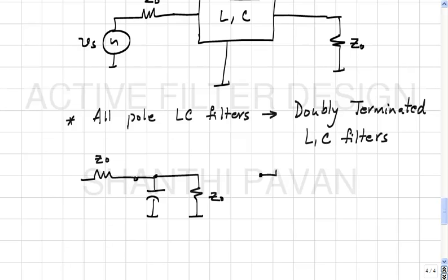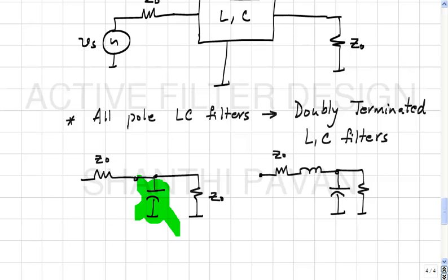When I want a low pass filter, if I want to use an inductor, then this is a low pass filter. Why didn't I put an inductor in series with the capacitor? That will also give me low pass operation, isn't it? It will have finite zeros. Putting an inductor in series with the capacitor at high frequencies, what will happen? The inductor becomes an open, correct? So therefore, at high frequency, the gain will be 1/2. But that's not what we want.